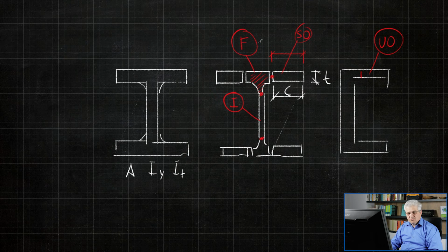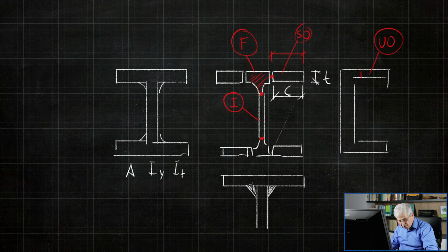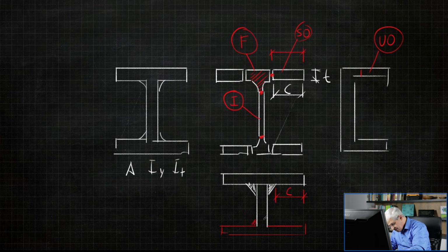In the Eurocode for aluminium there is a better explanation. Also, some additional parts, reinforcements, are explained there. But this is the basic which we will use now in SCIA Engineer. And then there is also one quite important part. If we have, let's say, an H section, I draw it in this way. Then we have welds or roundings. These parts in Eurocode are defined with this clear width. This is the c. It's from the weld to the end of the cross-section. And for example, for the web, it's this length. This is the c.